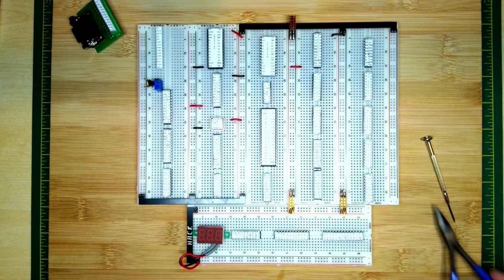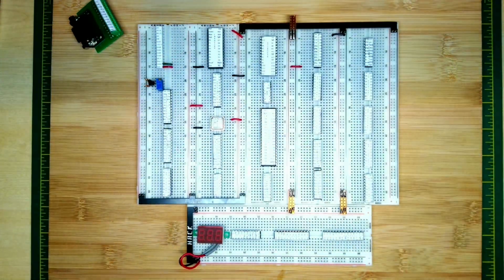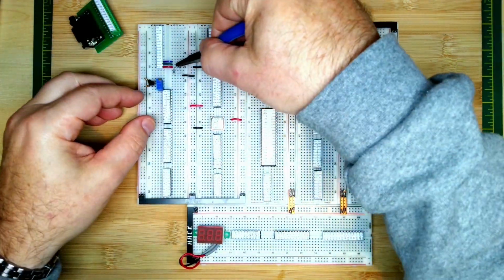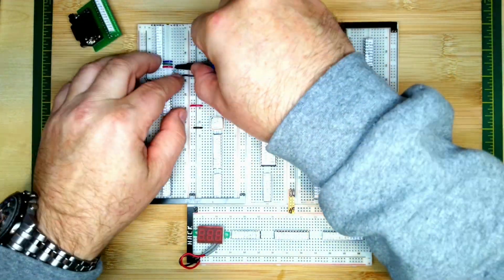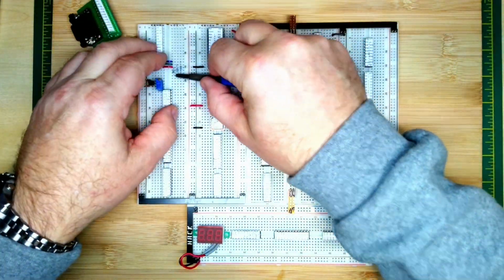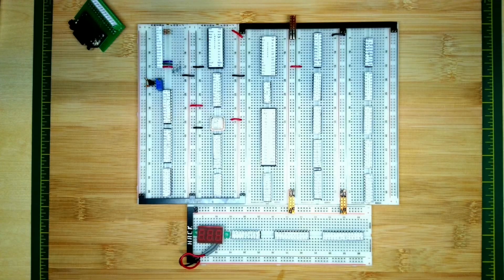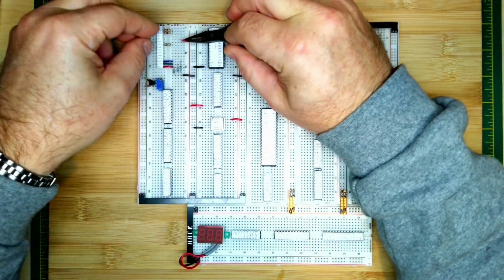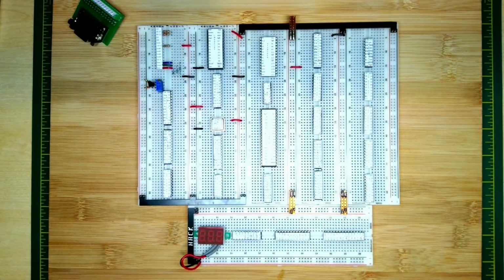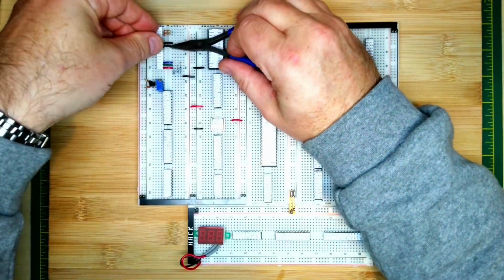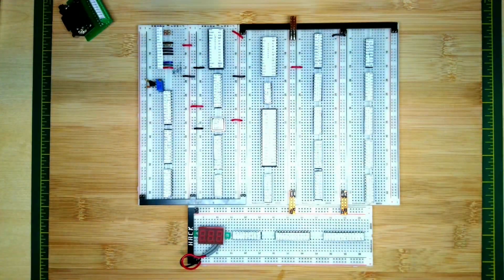Now we're just going to wire in the red, green and blue video lines. They need to be tied to ground with 75 ohm resistors to make sure the impedance matches with the monitor. Then the output resistors for the horizontal sync and vertical sync. There's a tie to 5 volts there, and then a lot of ground signals here which are just tying all these ground signals together.